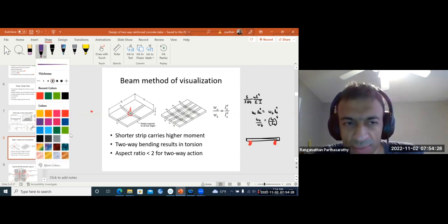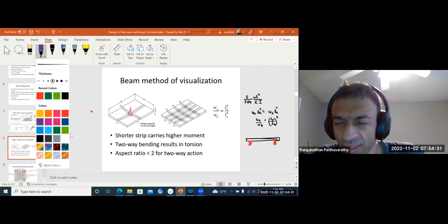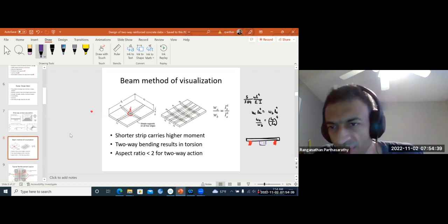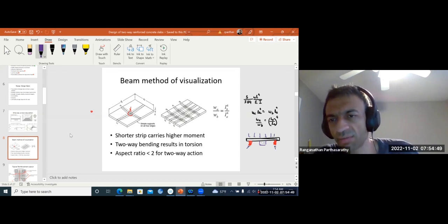These two red springs, you can imagine, are thick metal springs, and in the middle I just have a foam block. Now, when we put any load on this bed, that is when we lie down, almost all the load will go to the springs, because they are much stiffer than the foam block.